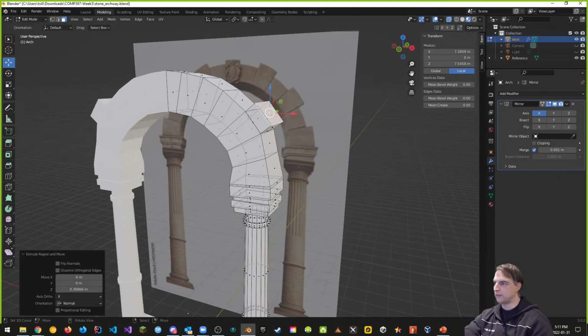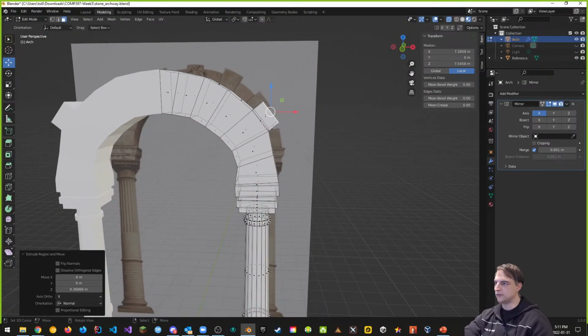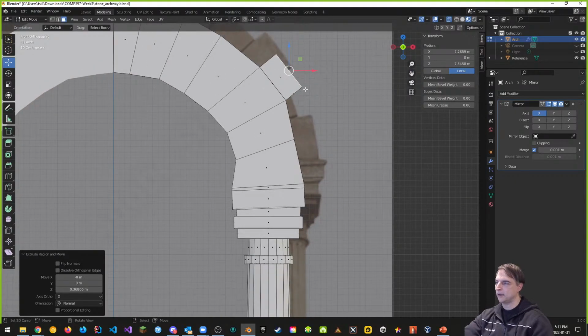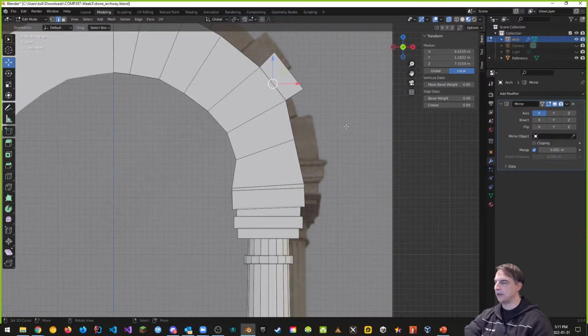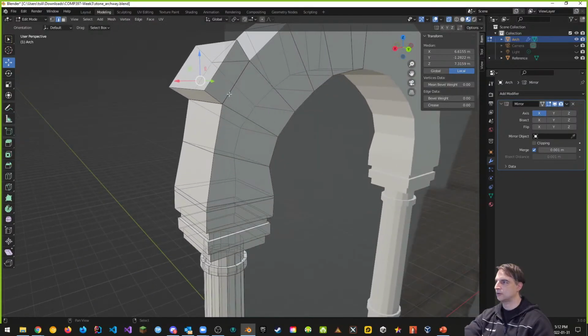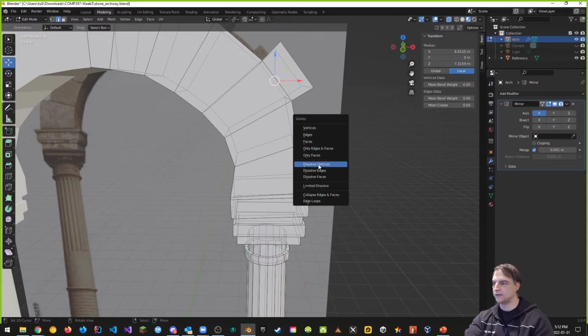And the way, first of all, we want to get rid of this piece as much as possible. So this line and this line, we definitely want to dissolve those lines when we do it, right? And we could probably first start off with a scaling, so scale, so we can make it as clear or close as possible. We're going to make some micro adjustments later, but we definitely want to now grab this edge right here, and this edge, right? And I want to dissolve if you can. So where it says dissolve edges, dissolve those two edges as much as possible.